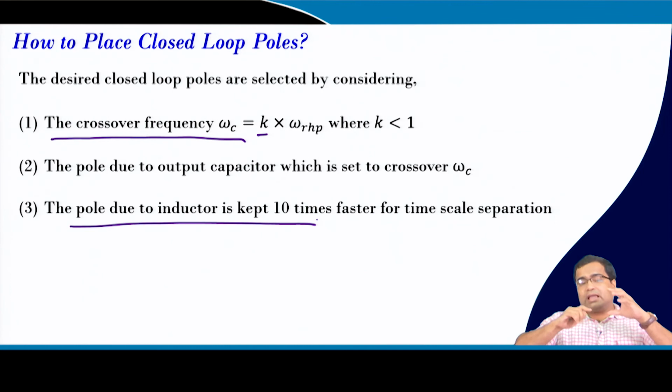That means in the loop transfer function we lost the control over the voltage pole because we have cancelled the pole, right, and that is one of the drawbacks of the output feedback approach, because of pole-zero cancellation the system may not be controllable.